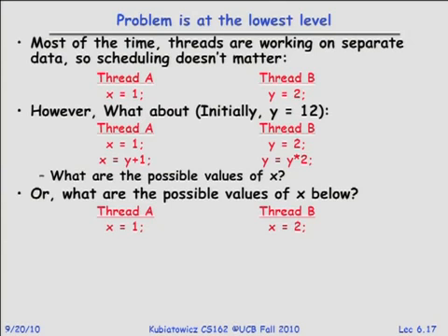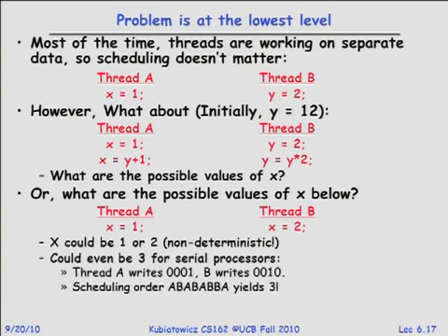Now, fortunately, none of the processors you are going to use in this class will ever do that. The reason is that loads and stores by themselves are atomic at the one-word level. So basically what you will see is either x is 1 or 2. You can't tell which, but those are all the options. You can't really interleave bits. There are certain types of hardware that might be writing things out in serial, and that could be a problem, but that's a pretty esoteric piece of hardware.